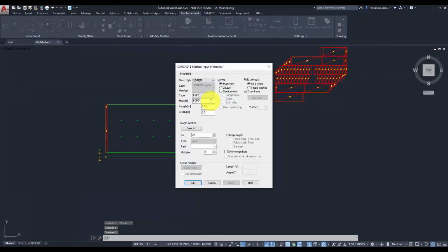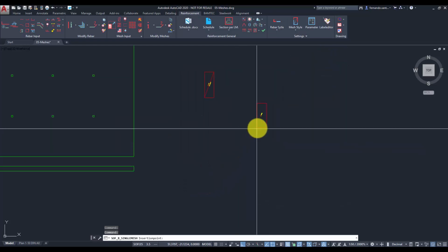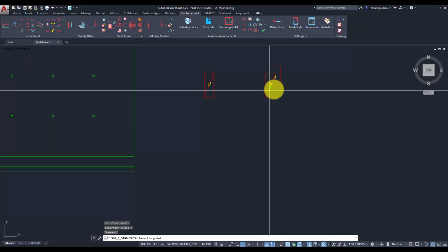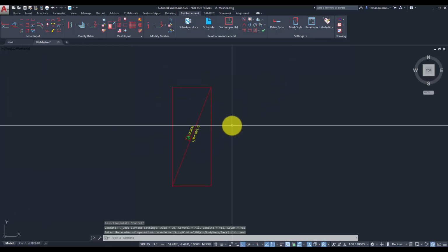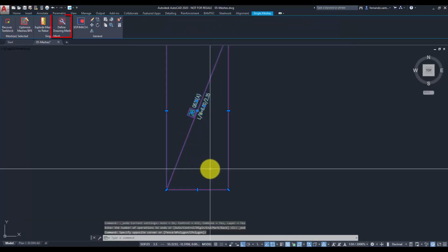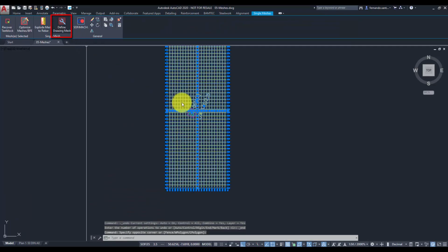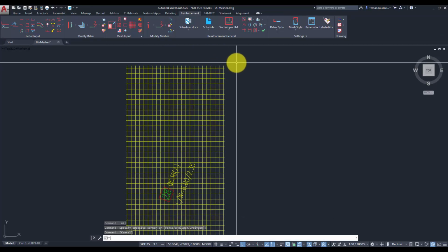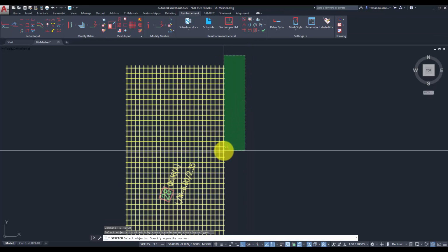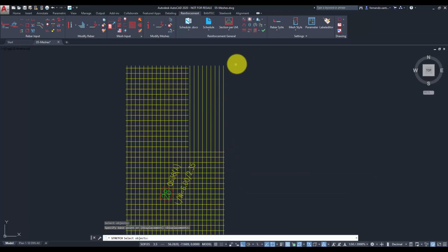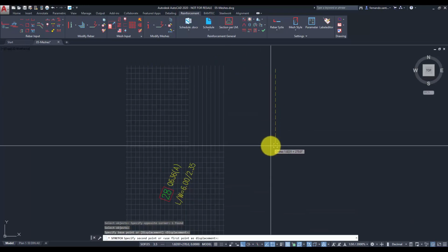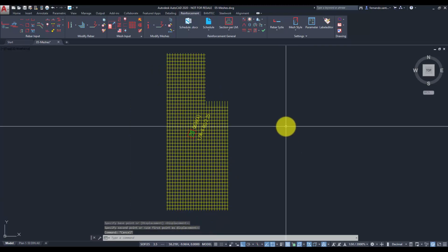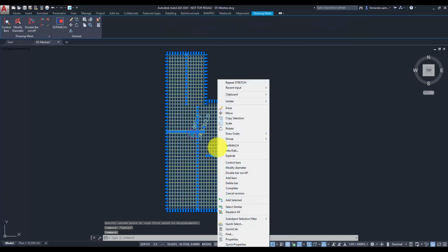In case we need an irregular mesh configuration, this can be achieved through the command, drawing mesh. We start out with a template mesh so similar as possible to that final mesh we need. After calling the command and selecting the template mesh, the sketch mode will be activated. Now we can proceed with the modifications. When we are all done, we select complete and name the new mesh type.